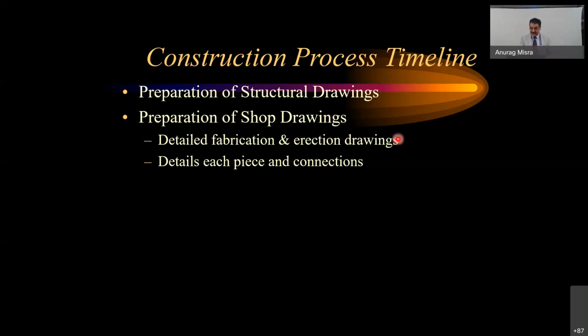prepared. So quite a lot of time is going, and that is why it is very essential that it is done in factories, so that this process becomes a repeatable process, and the manpower deployed there know how to draw shop drawings from the structural drawing, because steel detailing is quite strenuous and very important, because the tolerances are just a couple of millimeters.